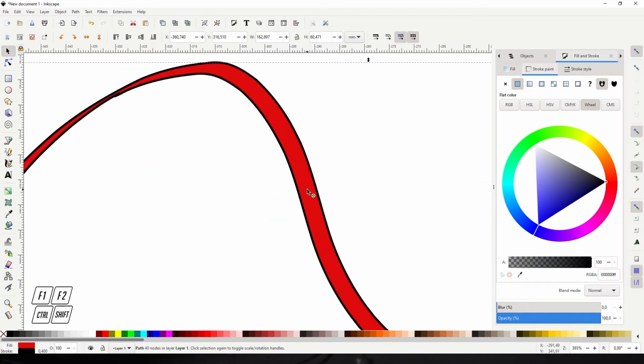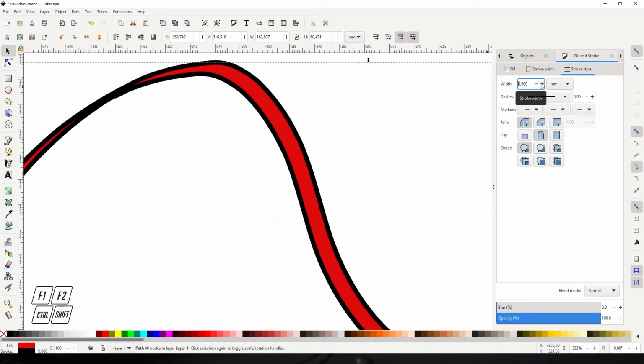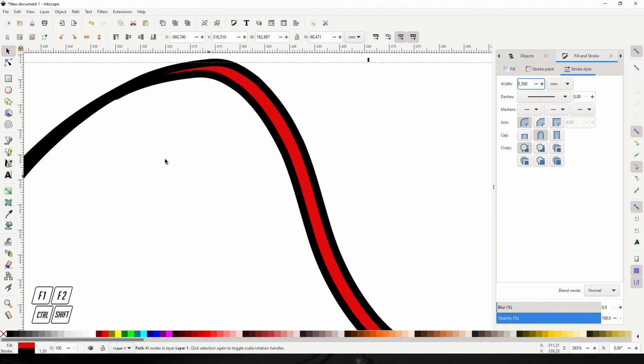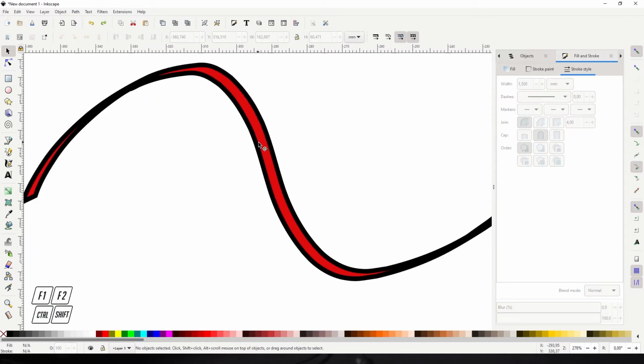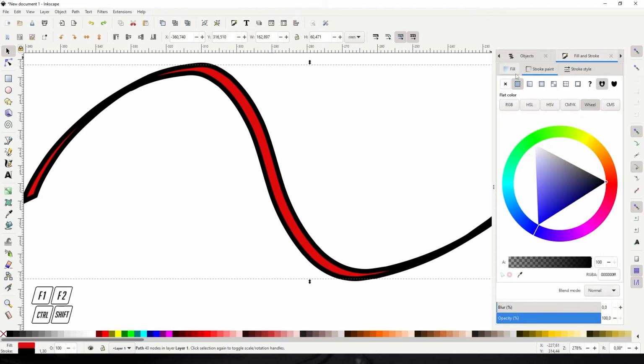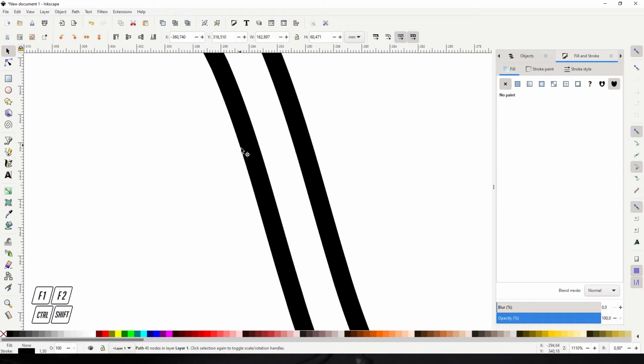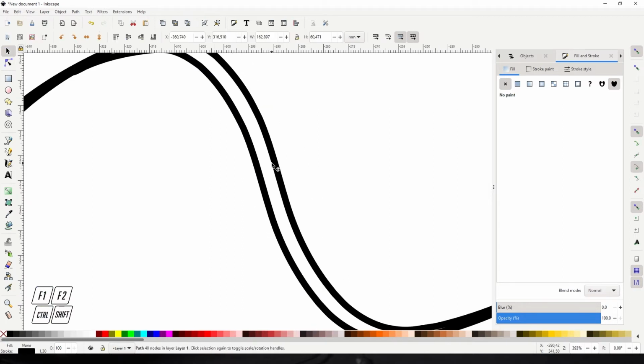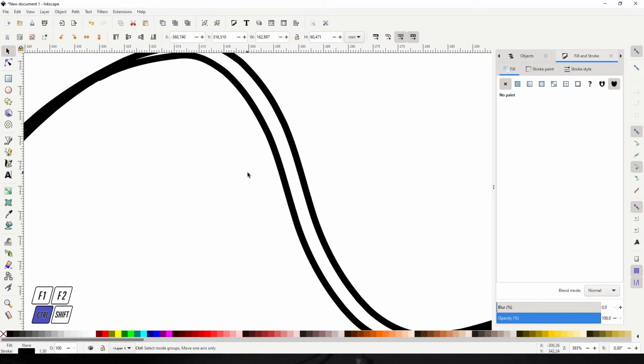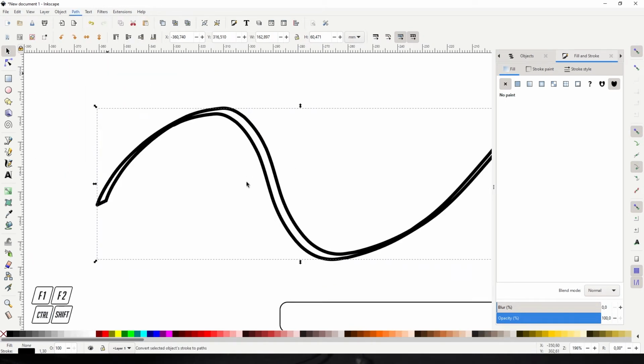Okay, cool. Now I'm going to increase the thickness of the stroke. Remember, this is irrelevant for cutting because the Origin ignores the stroke width. And now imagine I realize I want to cut this stroke, the black parts, not just recess or pocket cut the red area. I'm just going to remove that, but cut on the inside of that stroke and on the outside. And remember, right now it's just one very fat line. What we can do is select our entire shape now and select Stroke to Path.